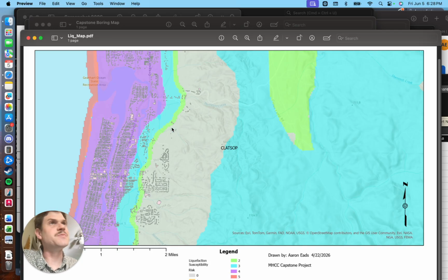And liquefaction is basically when an earthquake happens, the sand will liquefy, quite literally. So building dense, heavy buildings on the coastline can be a concern as far as foundation and what kind of foundations you want to use. So that was the whole idea behind this report.